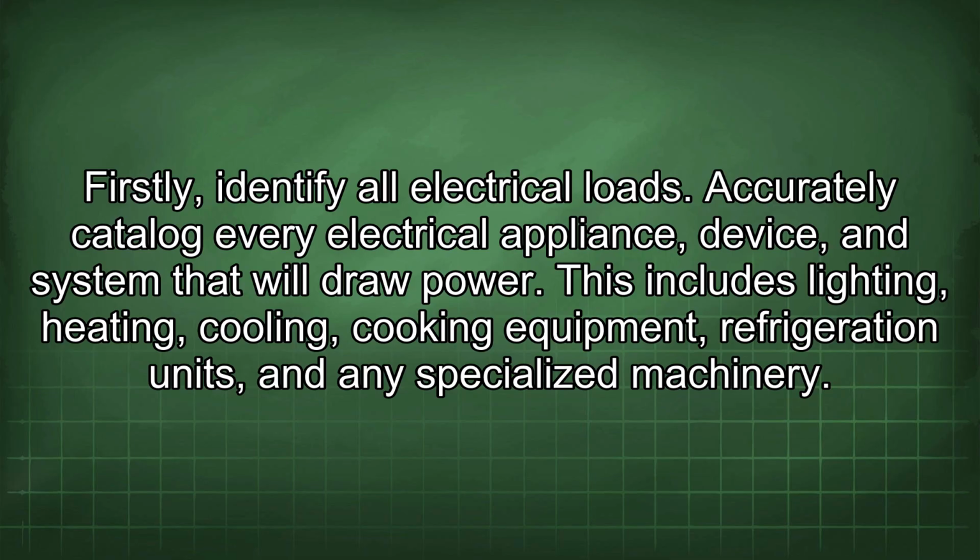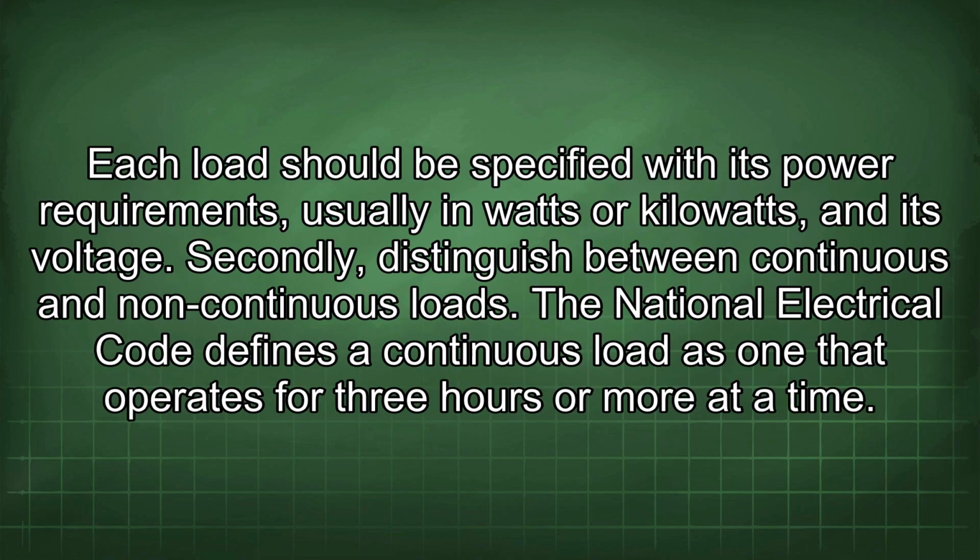Firstly, identify all electrical loads. Accurately catalog every electrical appliance, device, and system that will draw power. This includes lighting, heating, cooling, cooking equipment, refrigeration units, and any specialized machinery. Each load should be specified with its power requirements, usually in watts or kilowatts, and its voltage.